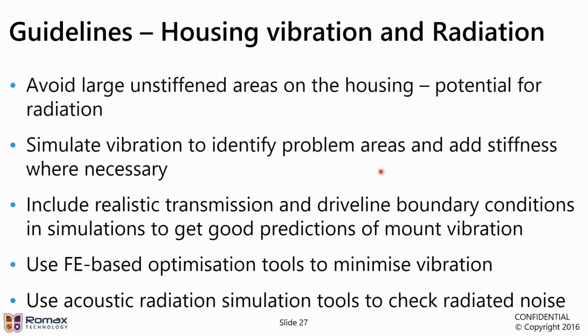In terms of housing vibration and radiation, in general, we want to avoid large unstiffened areas on the housing that are going to resonate a lot, essentially acting as loudspeakers.